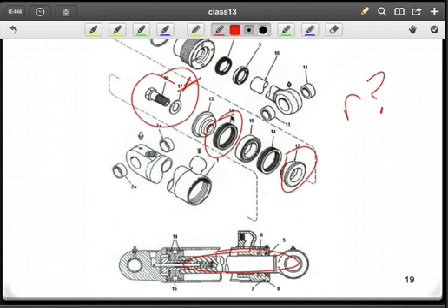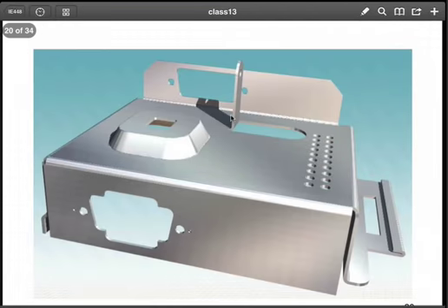Now in this case with an assembly, if we detect that it is not functioning and therefore it's defective, we can disassemble it and then add the necessary components. In other words, replace them if they're defective or if they were not assembled in the first place. And so for an assembly, R tends to approach 1 because of this ability, in most cases, to be able to disassemble the product and then reassemble with the correct parts.